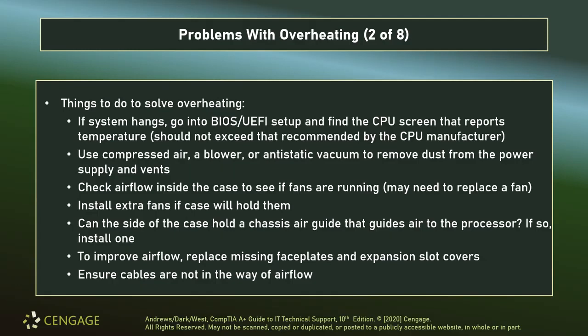Also make sure that there's not cables in the way. You don't want things just kind of hanging that could block the fan and cause it to lock or stop. You also don't want a cable to accidentally become damaged by impact with another object.